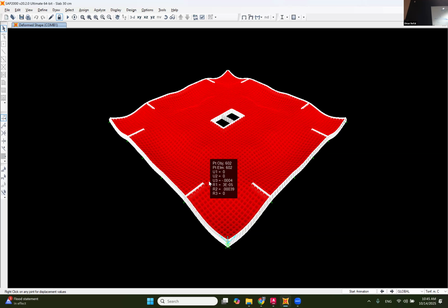But if you want to make this beam act more like a wall, you pick all these joints and assign a hinge, like this joint and this joint and this joint, and assign hinges at all of them. So that's also another way. You can pick a flexible beam and put hinges at all the points on this beam. So there are multiple ways to do it.